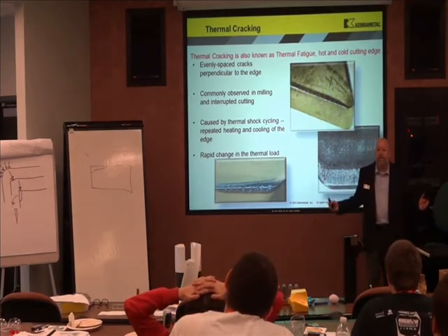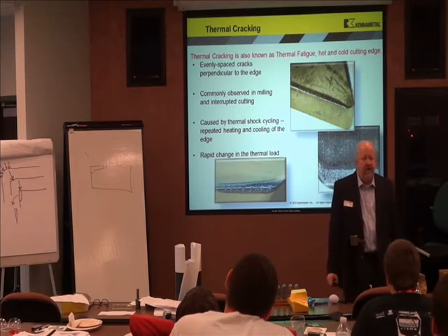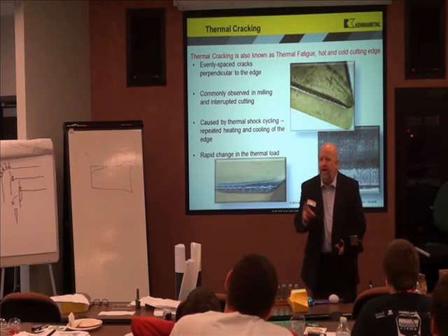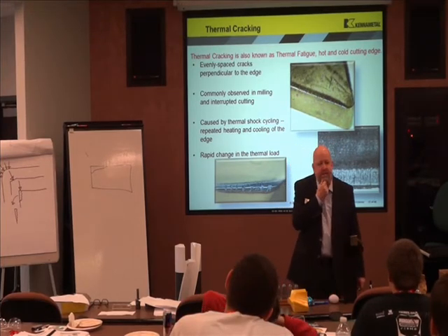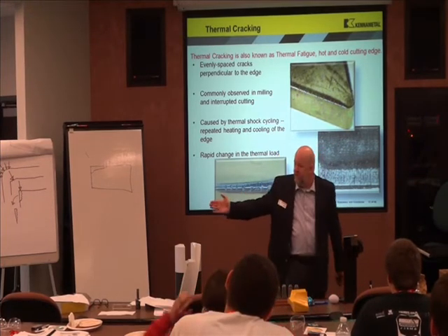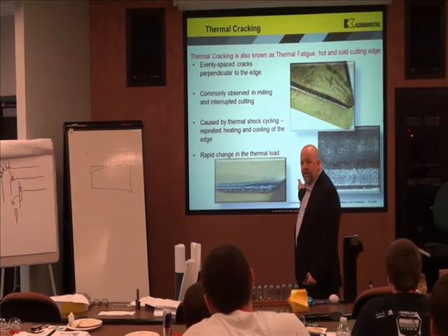Thermal cracking. What happens when you put hot water on a cold windshield? It cracks. Milling. How hot is it at the shear zone? 1200 degrees. Now when that insert in the milling cutter is in the cut, it's 1200 degrees. When it comes out and you put coolant on it, what do you think you're doing to it?